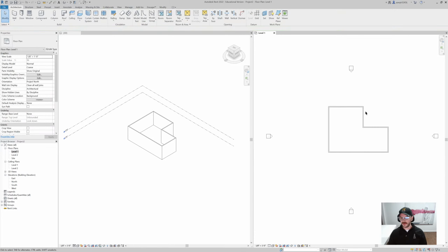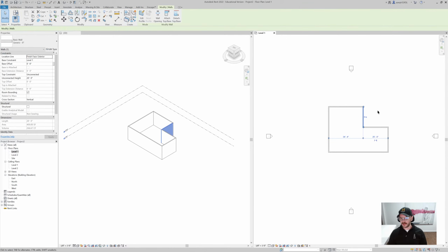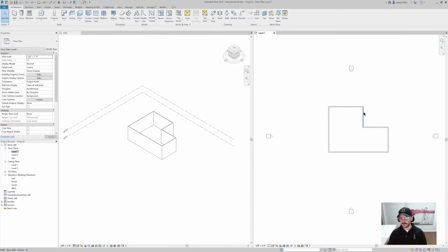Whenever you're in Revit, right, you can hover over an object to select it. Once you have it selected, you can drag it. Once you're trying to select an element, let's say you want to pick all these walls, you can drag a selection window over it. If you select it from right to left, it'll select any element that's within the bounding box.